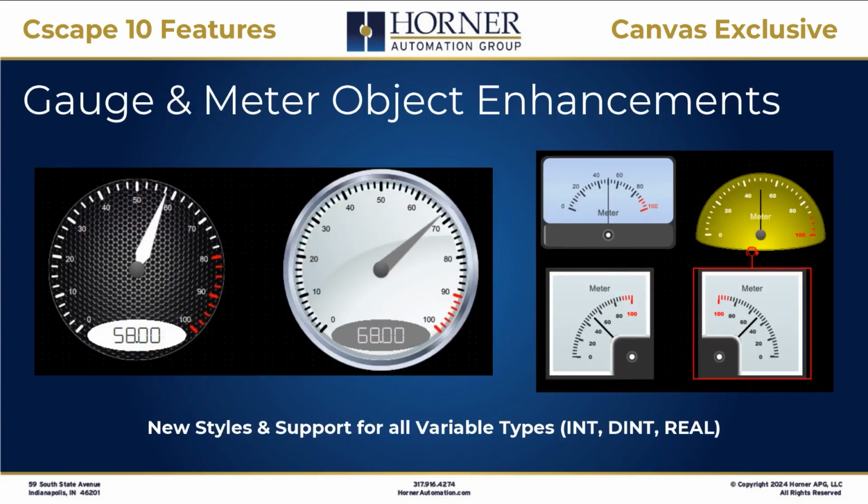Gauges and meters have been enhanced with new visual options, as you can see here on the screen. But one of the biggest updates, and this applies also to bar graphs, which I just talked about a minute ago, is that now you don't have to have an integer-based variable in order to have a gauge object on the screen. So if you had a real variable that you wanted represented by a gauge, with Cscape 9, you need to also create an integer version of that variable that the gauge can be tied to.